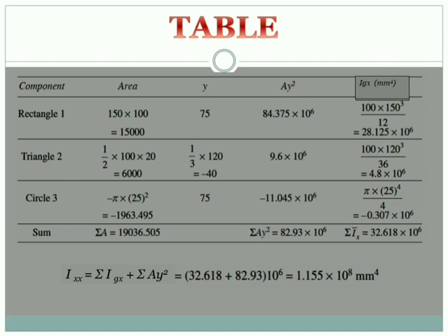So we have a direct formula for the centroidal Ig value with the base as the axis. When we discussed the formulas, this was told. For a triangle we have two sets of formulas: one with respect to the CG axis, and one with respect to the base. Here we can use it directly because our xx axis is itself the base of the triangle. See the figure, it will be clear.